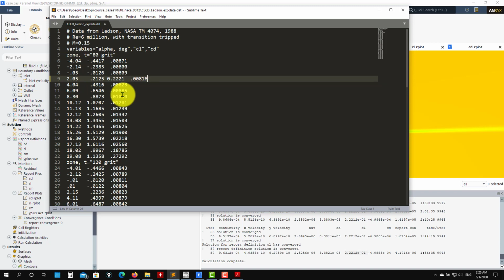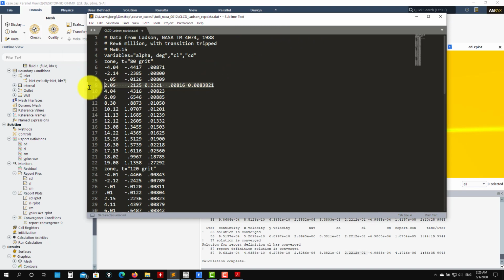And then the next one was 0.008381, not bad, okay? So see that, and then this is the playground, because now go and use K omega SST, K epsilon, Reynolds stresses, any of the other turbulence models, and you will see that there will be some differences. So each turbulence model will give you different results. Hopefully they will be all close to these ones, okay? But this is the idea of turbulence model.